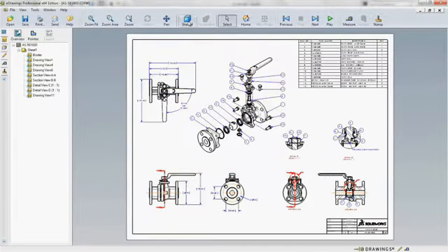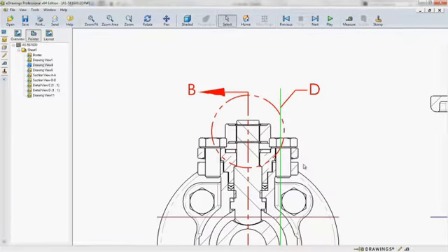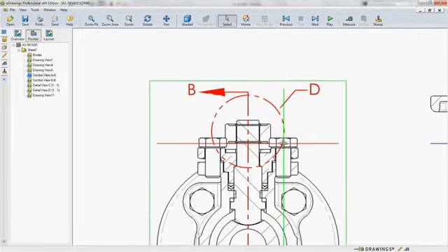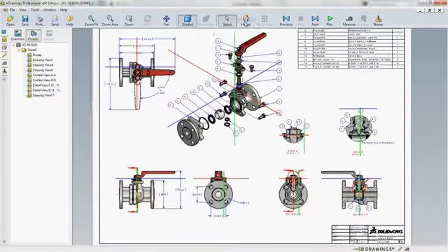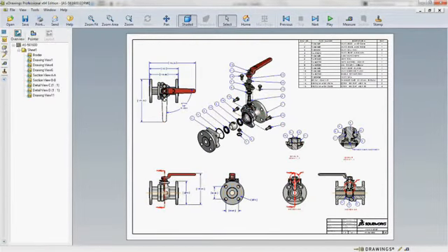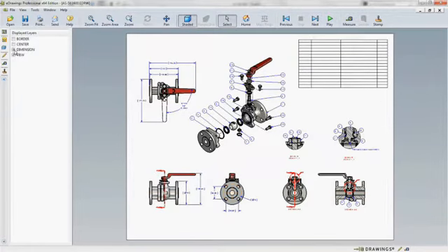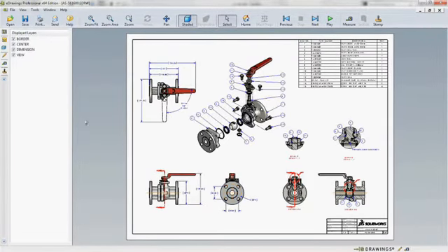Another tool that's extremely useful for non-engineers is the pointer tool. As you drag it around, it moves the pointer relative in every view on the drawing. This makes it easy to find things, such as a hex cap screw. If dimensions or other drawing items are getting in your way, you can toggle the visibility of any of the layers in the drawing as well, ensuring you can focus on what's important to you.